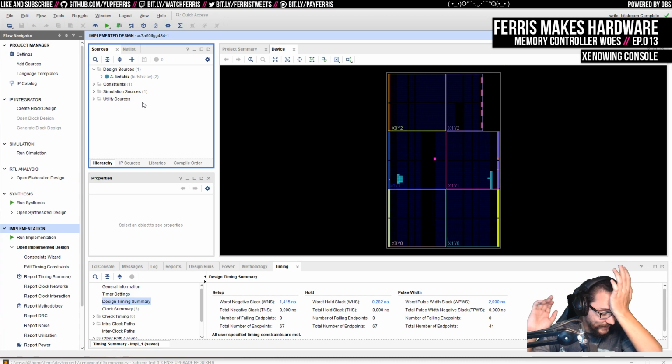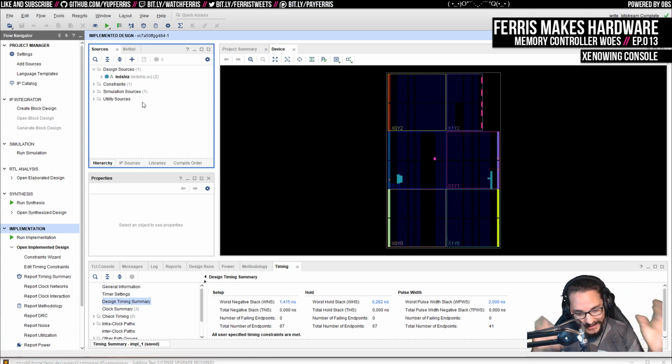The other thing I did, I forgot to mention, is on the Max 10 project where I was just doing everything bare bones, I also learned how to use a PLL to generate a specific clock frequency. So I was playing around with the clock frequency and seeing how high I could go, and that was kind of fun. But again, making sure that I did that in combination with having proper design constraints to just get a feel for even putting together some of these basic blocks. So I also did that in this Vivado project as well.